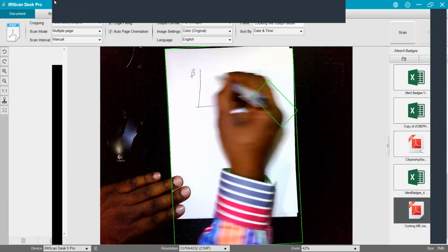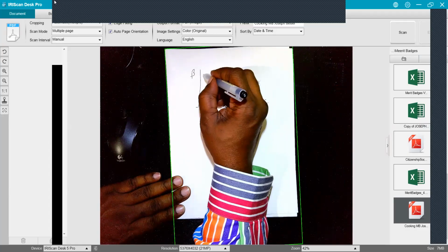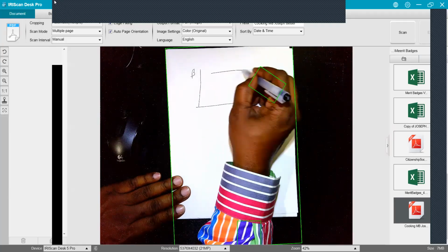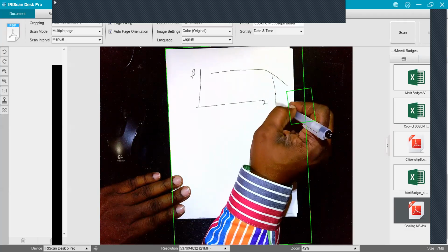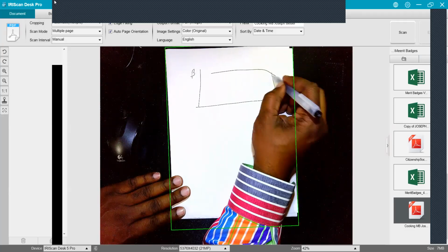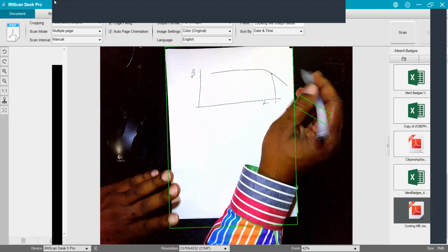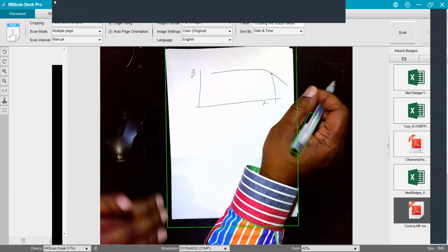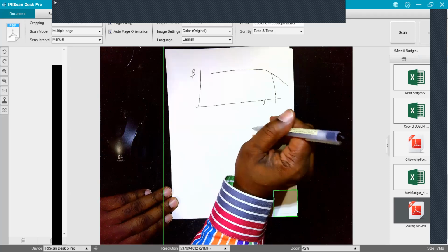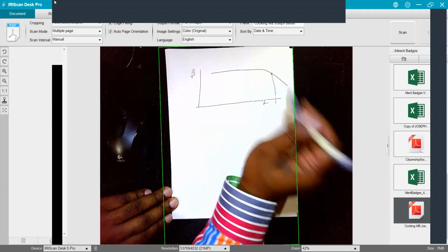Well, beta doesn't stay flat forever. At some point, it'll start to roll off also. This is what gave us one of the other poles that wasn't associated with either an internal capacitance or an external capacitance.